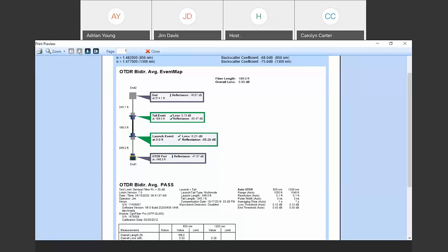When we're doing loss testing, we talk about an overfilled condition, and we use a mandrel, or this puck, to get encircled flux compliant situations. So, direct answer to your question, in the OTDR world, we are not going to use a mandrel.